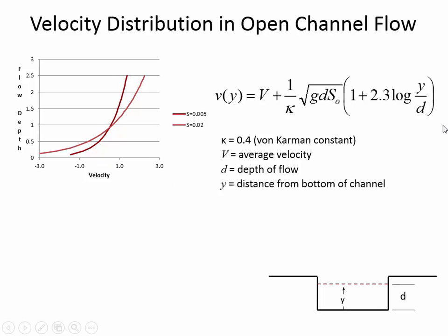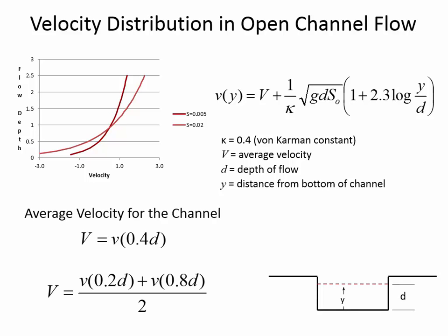And so usually this equation is only used to describe the velocity within the top 2/3 of the cross section. The bottom third, where the velocities become negative, it's not accurate. Once you have an equation like this, it sort of loses track of the fact that sometimes you can do a physical measurement and get a pretty good idea of what the average velocity is by sticking a flow meter into the actual physical stream and averaging it.